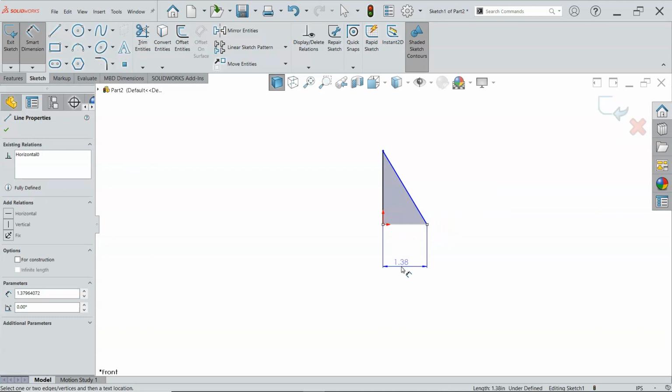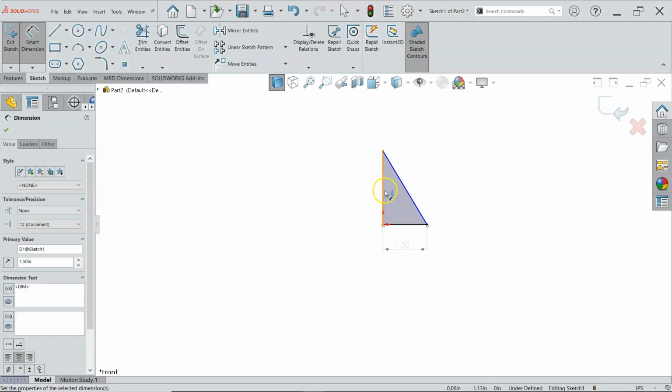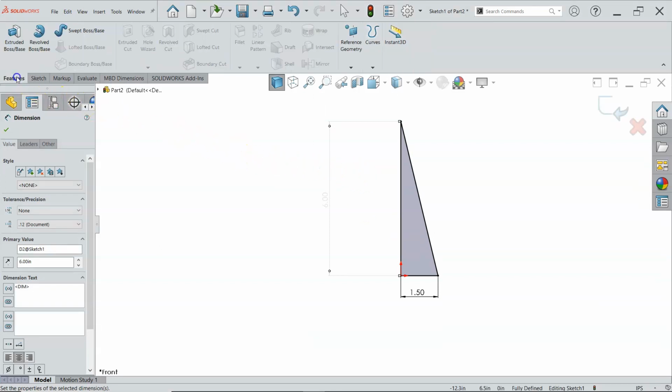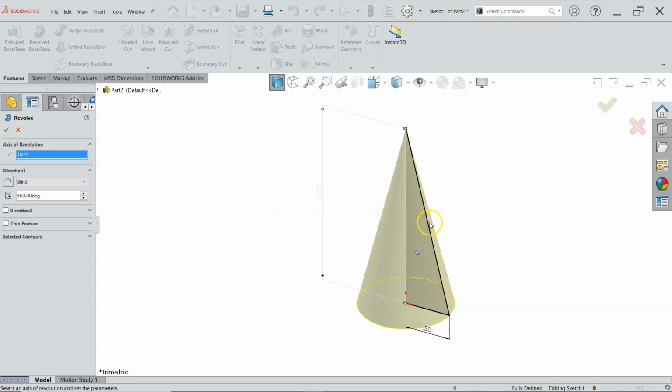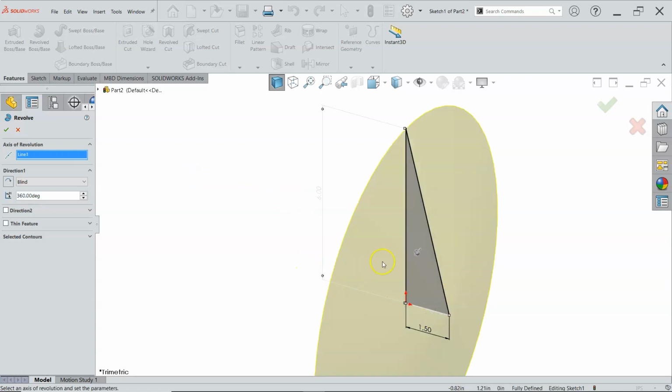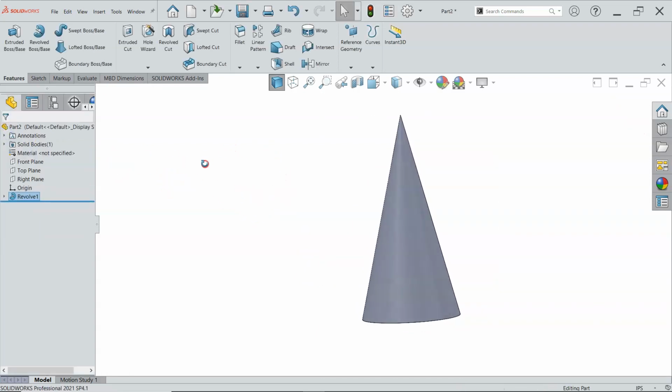All right, so if I make the base, because I don't have that center line, I don't get the diametral, and go to 1.5 for a 3-inch base and 5 inches for the top. So if it was going to fit inside of the previous cylinder or something to that effect, I would want to create those geometries. All right, so we have a revolve, no center line. It says I'm waiting for you to pick something. And again, as long as it's not self-intersecting, I can create those geometries as I go through the process. All right, and we'll have our first solid body for the cone.